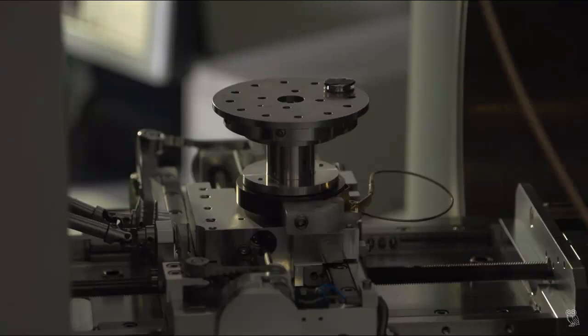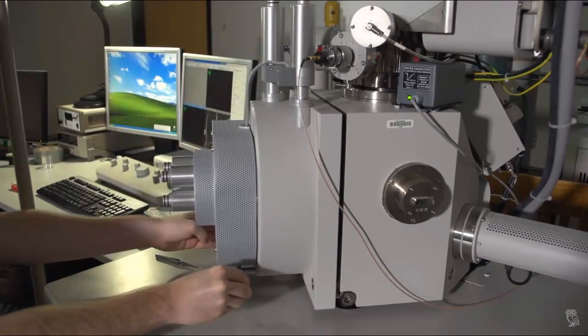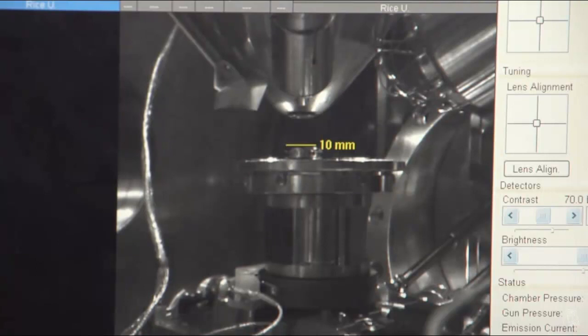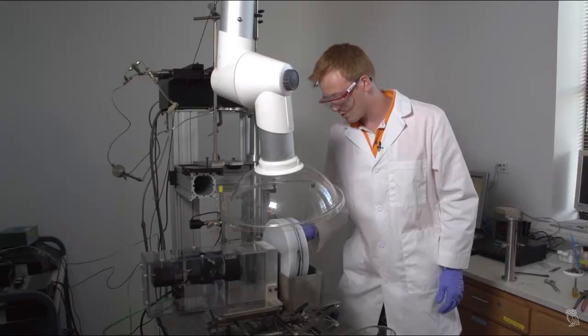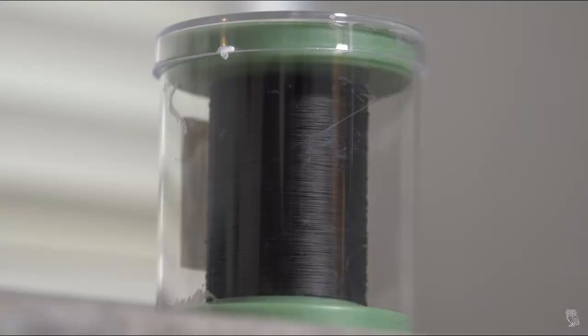The machine we're sitting near here is the SEM, the scanning electron microscope, and we use this to do high magnification imaging of the surface of our fibers so we can get an idea of what the structure is on a microscopic scale, the scale of a couple of micrometers or a few nanometers, tens of nanometers. The cool thing about it is you have a material that's very strong and highly conductive, so it has properties like high-strength materials like carbon fiber. But on the other hand, you can handle it essentially like a textile, not like a rigid material.